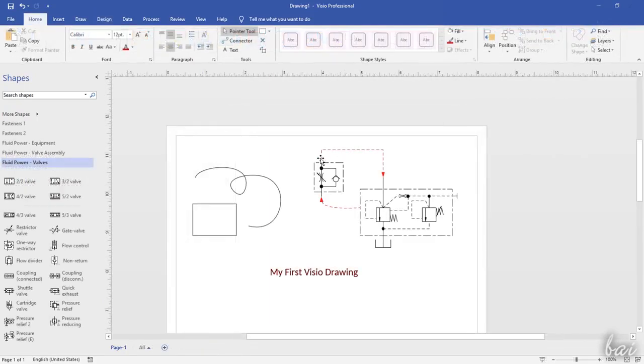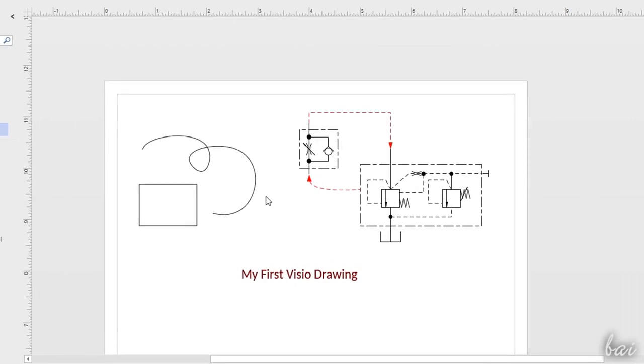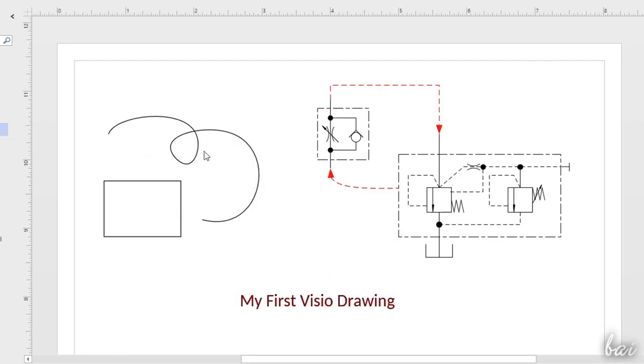Once the page is ready, you can start drawing inside your document. This is made of three main kinds of objects: the shapes, the connectors, and the pieces of text. Shapes are simple objects like rectangles, circles, lines, but also complex ones like motors, buttons, and icons showing topics and representing subjects. The connectors are wires and arrows connecting shapes and showing relationship and dependence between these. Pieces of text are titles and annotations used to name or describe your objects.